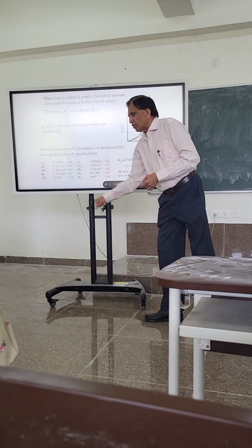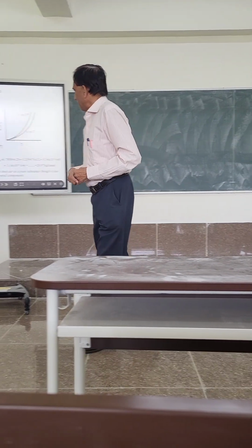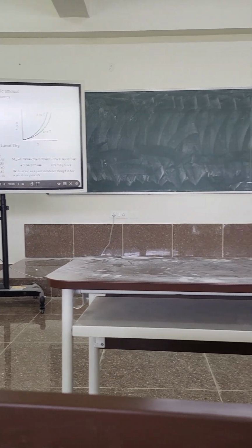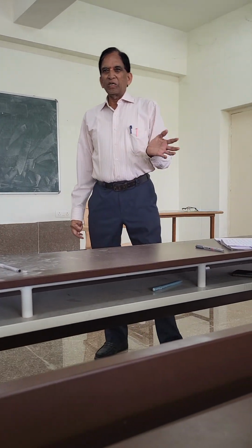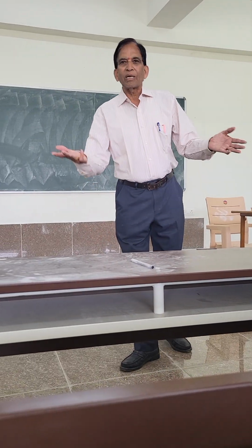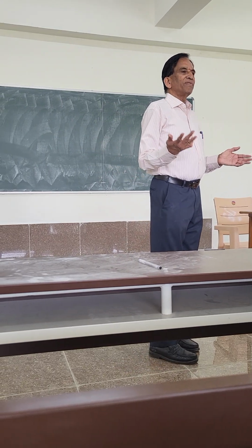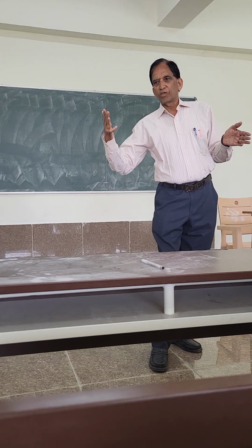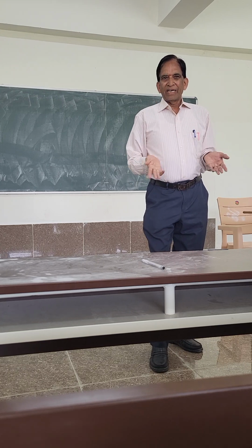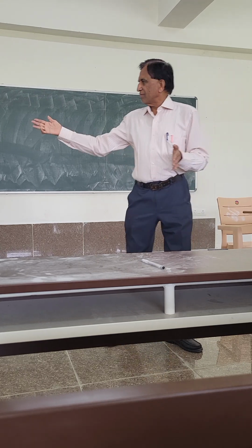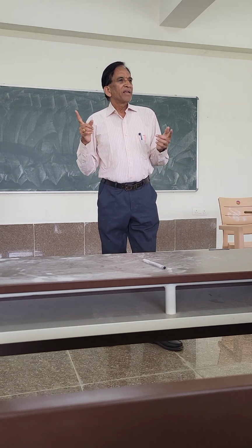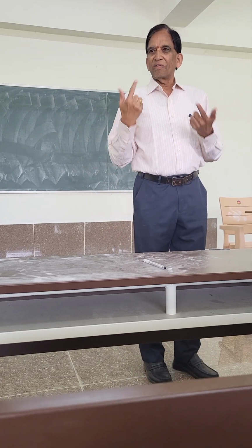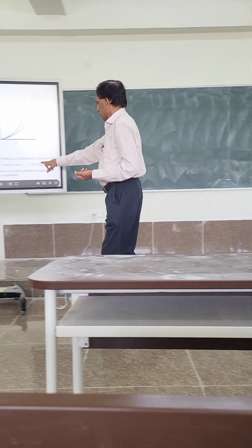All the other things are also done. They don't make much of a contribution. So finally, we see that the molecular weight of air will be 28.97. I'm quite happy if you round it up to 29. 28.97 is pretty close to 29. So for all practical purposes in our thermodynamics calculations, we take the molecular weight of air as 29, which is also reasonable because nitrogen is 28, oxygen is 32. Most of the air contains nitrogen, so it has to be closer to nitrogen, but we have got 29. So remember, molecular weight of air is 29. This will be chasing us for the rest of your life. So that's all about the molecular weight of air.